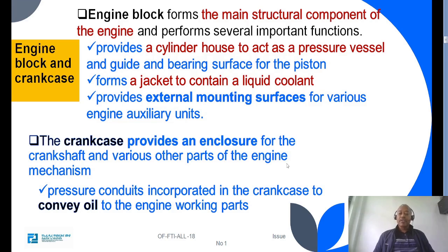Engine block and crankcase. The engine block forms the main structural component of the engine and performs several important functions. The engine block provides a cylinder house to act as a pressure vessel and guide and bearing surface for the piston. The block forms a jacket to contain a liquid coolant. It provides external mounting surface for various engine auxiliary units.